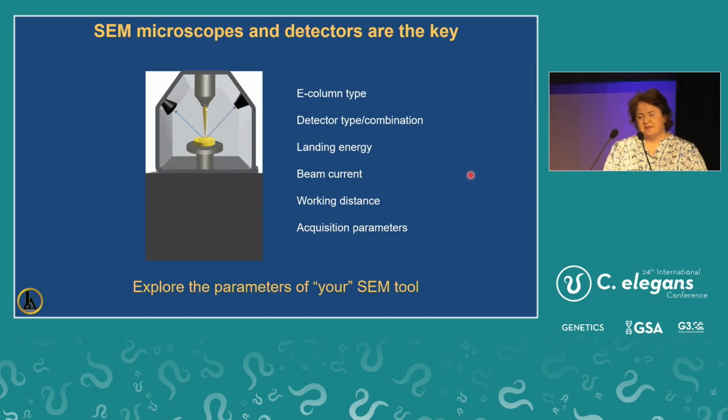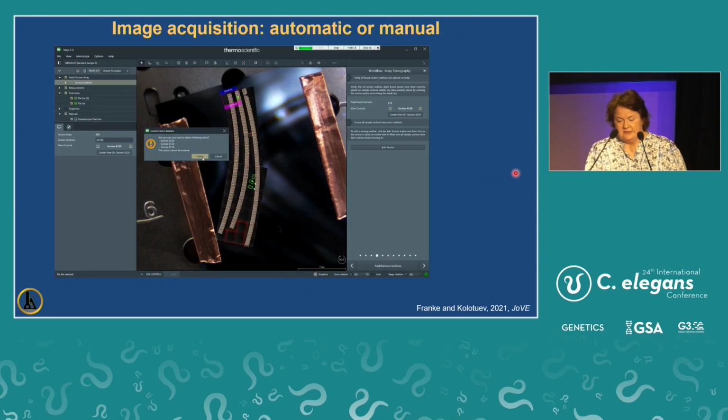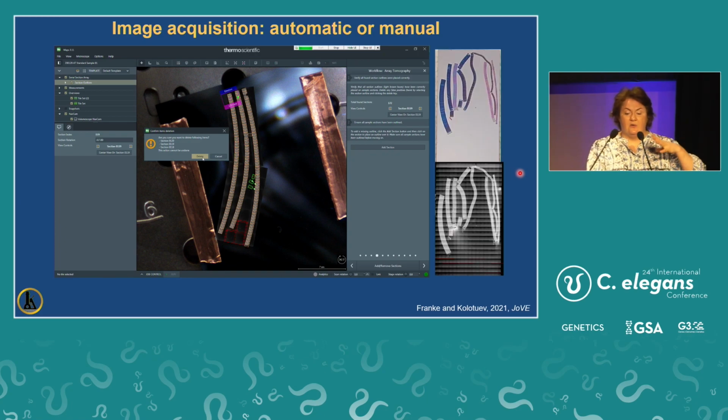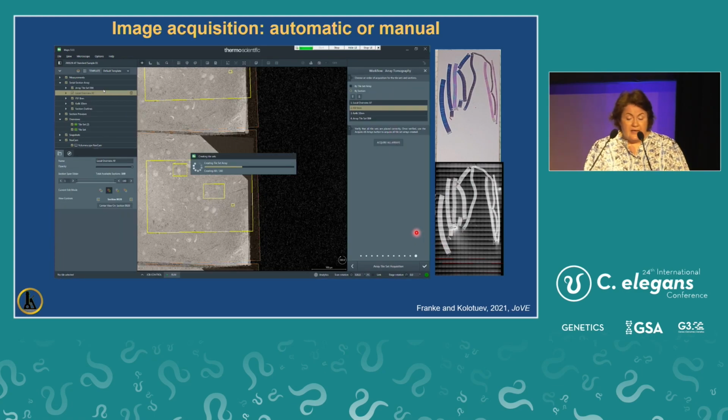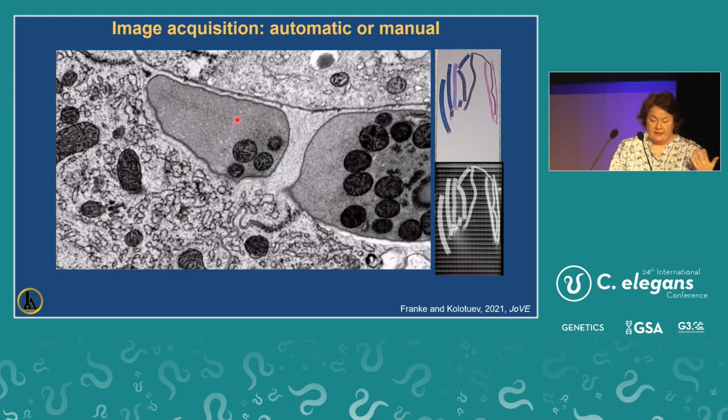and it's important not to say, oh, it doesn't work, that's all. There are so many things that you need to play with, and it will work. So basically, you can have either automatic or manual acquisition of the sections on the array. I'm using the FEI MAPS, in which you can see the wafer, and that's the map of the same wafer inside the microscope. When you find the regions of interest, you can decide what you want to collect, in which sequence, and how it will look.